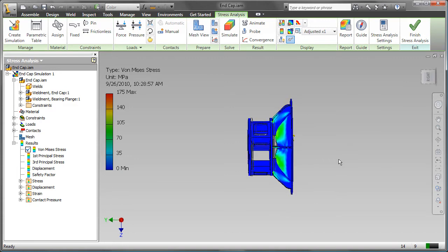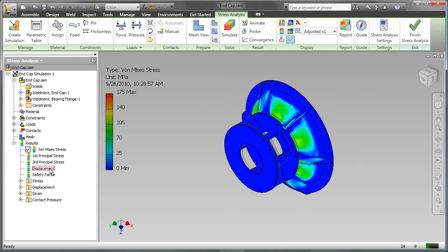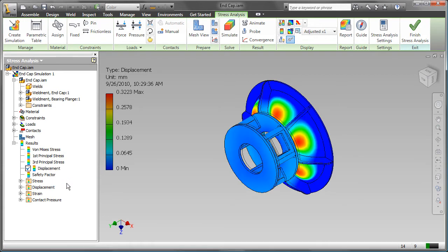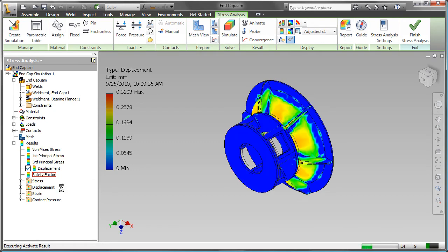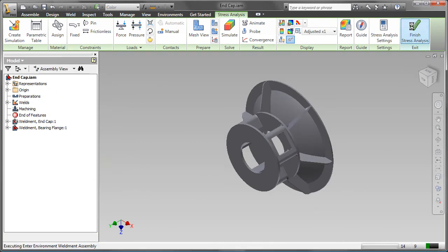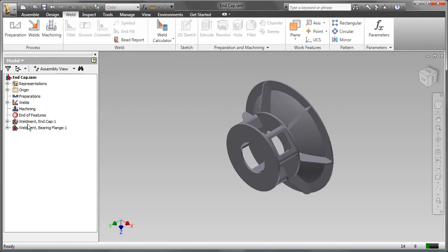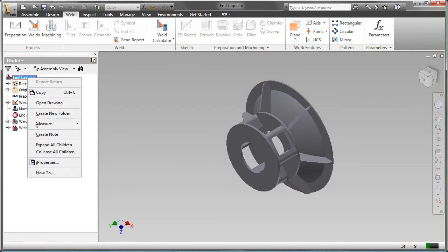In conclusion, the design criteria of 12 mm wall thickness, 160 mm end cap height, and 6 ribs is the preferred design. This design reduced the mass of the assembly from 295 kilograms to 231 kilograms. This saves 64 kilograms of steel per end cap and is a 22% reduction.